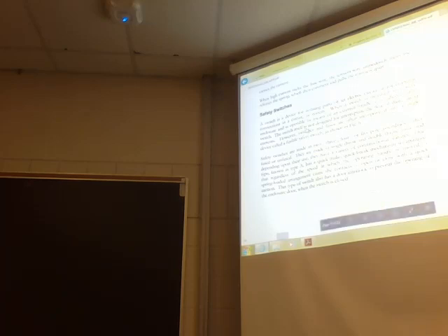Safety switches are made in 2, 3, 4, and 5 pole assemblies, which means the number of conductors that it's opening or closing, and they can be either fused or non-fused. They are made in single throw and double throw units, and depending on their use, they have a variety of constructional features. One type, known as type A, has a quick break mechanism so arranged that regardless of the speed at which the operating handle is moved, a spring-loaded arrangement causes the contacts to open or close with a quick motion.